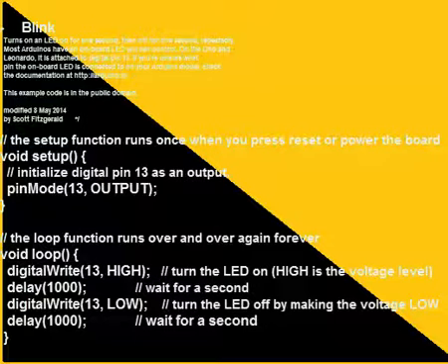For single line comments, you will put a //. For your variable block, that's the variables that you set up in the variable block to work in your functions. You will have a void setup function and a void loop function. All of these are required when you're doing code in Arduino.